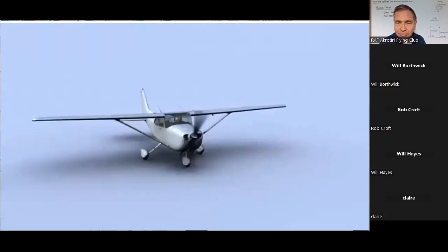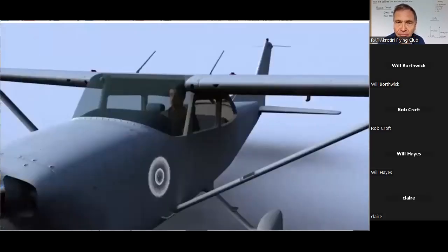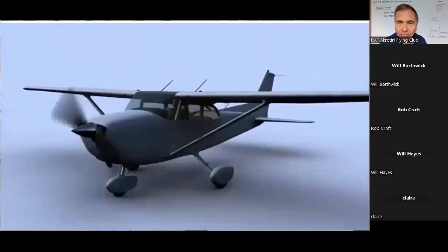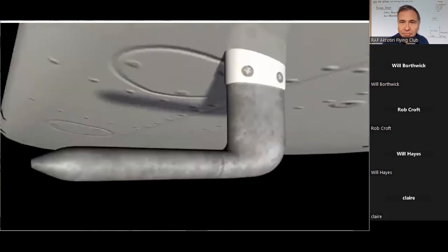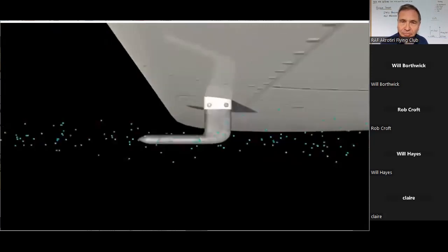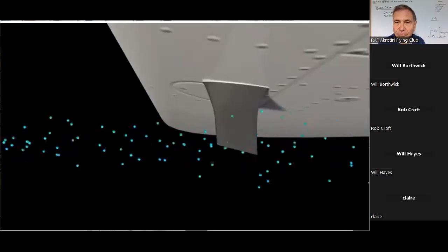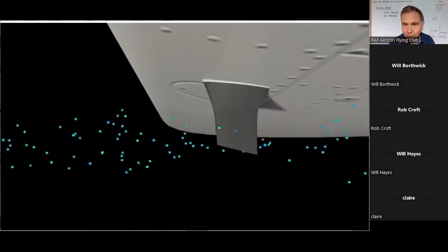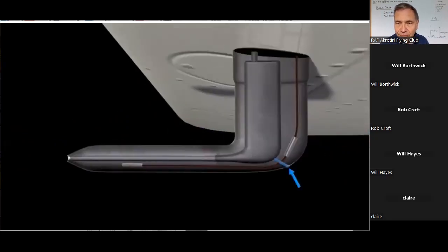The pitot-static system gathers its pressure information from two sources, the pitot tube and the static ports, hence the name pitot-static. The pitot tube is designed to measure the pressure of the air as the airplane flies through it. In most smaller aircraft, this tube is located under the wing so it can measure the flow of air without any interference. Sometimes aircraft manufacturers will use a pitot mast instead of a tube shape, but it still functions exactly the same way. On the backside of the tube, there is a drain hole, which allows any rain or water that is collected while flying to drain out and not go into the system.